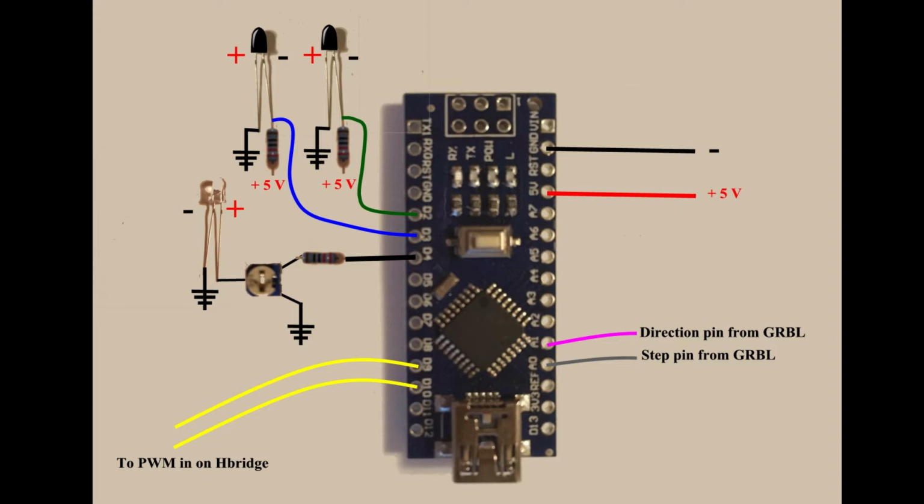This controller design works with a GRBL control board. It is designed to run on an Arduino Nano with an H-bridge, DC motor, and a home-built infrared encoder. A 3-axis CNC machine would require each axis to have a separate Nano-based controller and associated hardware.